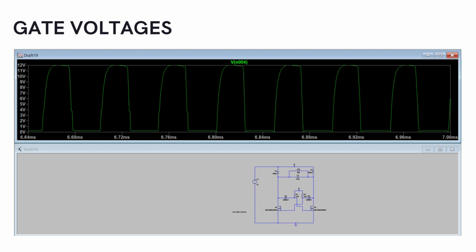So as we can see from the plot, the reason for the flat line is as follows: when the drain of the transistor switches and the drain voltage changes rapidly, the fast change through CGD creates a negative feedback to the gate and won't allow the gate voltage to change easily as long as the drain voltage is switching, hence creating a flat voltage area around the threshold voltage when the transistor is switching and the drain voltage is changing fast.